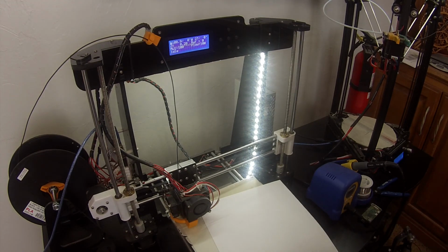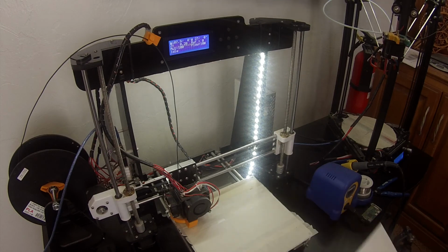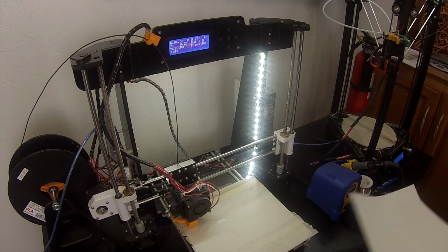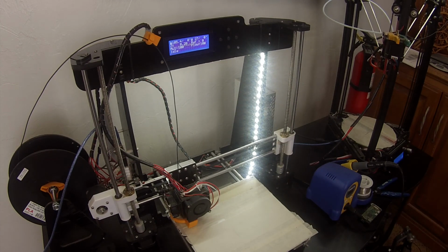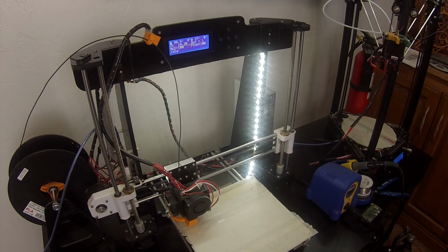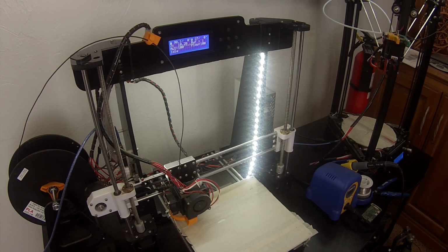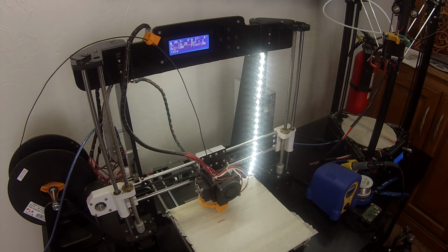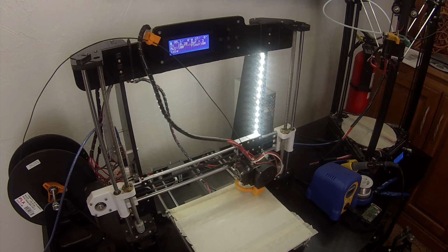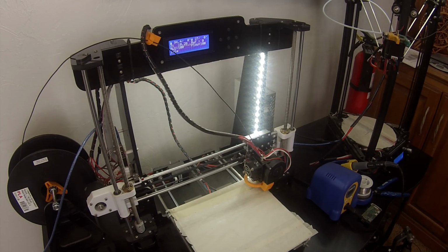I'm not going to adjust this printer's level right now because it's fairly tuned in and has been successful across the entire bed. But if you repeat that process with the assumption that the aluminum that makes up the bed is reasonably planar, then really you might only have to do this at perhaps 3, but usually I do the 4 corner points to get the best level that I can across the entire print bed. So you simply just move it across to check the other corner. Whoops, a bit far, but that's okay.